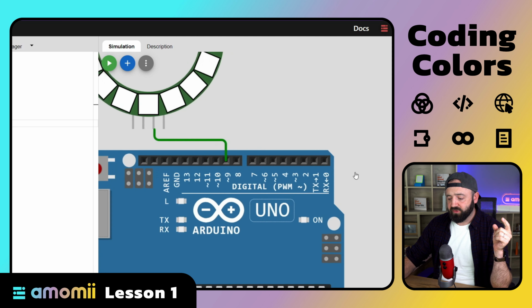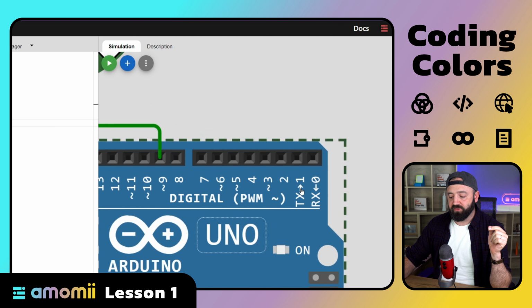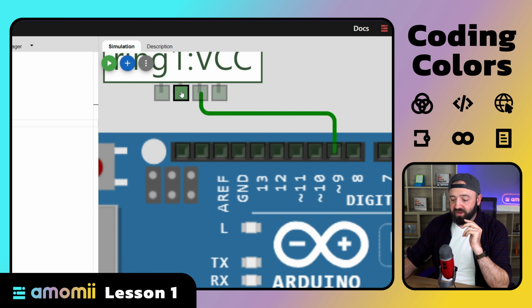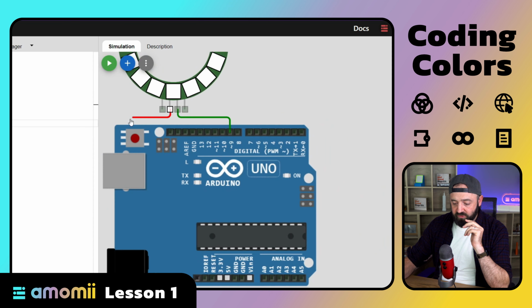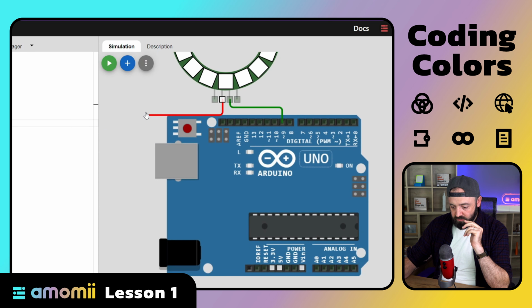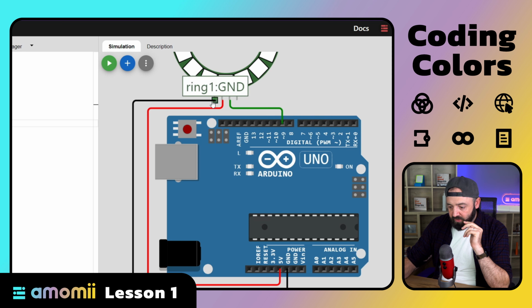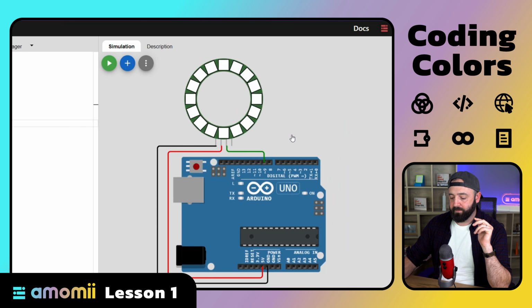However, just a quick note, we usually avoid pins 1 and 0 because they're used for data transfer between your computer and the Arduino. Next up, we can connect the VCC pin to 5 volts. And we can connect ground from the Arduino to ground on the LED ring. Okay, that is done and we could start coding it now.